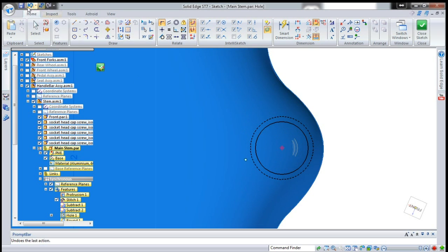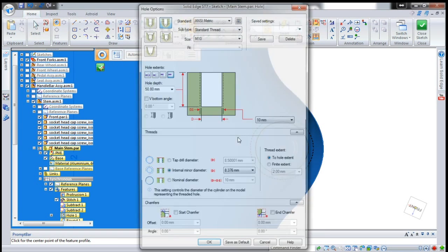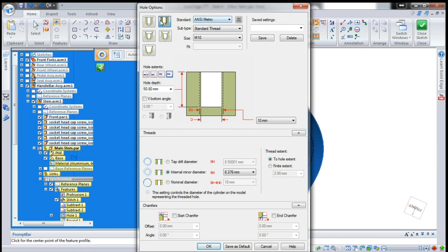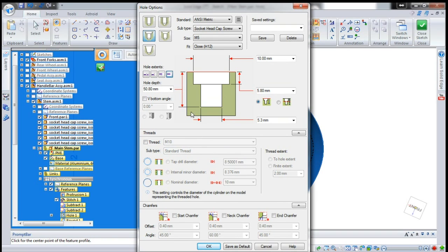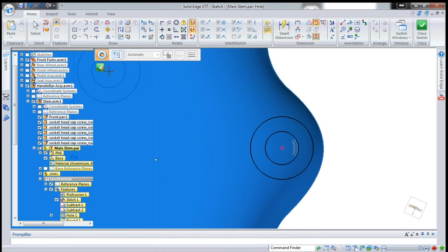There we go. However, I haven't specified my hole type yet either. What I want is, this bolt is an M5 bolt. I need a counter bore to suit my M5 bolt, and I don't want a thread on this component of it. The other thing I want to choose is I want my hole definition to be at the top of the hole and the bottom of the counter bore. So I simply choose that option. I'll make sure the counter bore has enough distance to go out the top, and I want the type of hole to be through next.